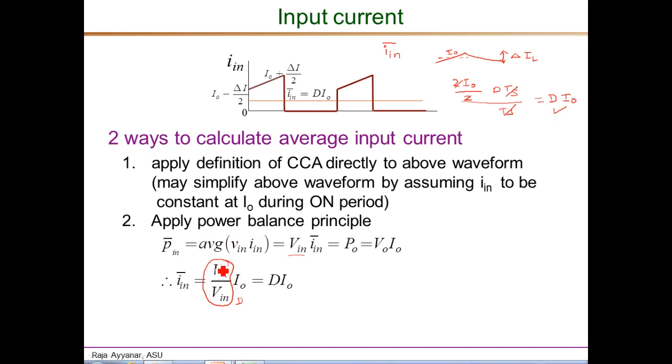Now this is an important concept. We can use this effectively to obtain different average values, most importantly average input current values. So another way of writing the power balance is simply to say that VO over Vin, which is the first thing that we derive for most converters, is exactly equal to Iin over IO. Notice the reversal in the input output. So VO times IO equals Vin times Iin. That's where this comes from. And for a buck converter, this is equal to D.